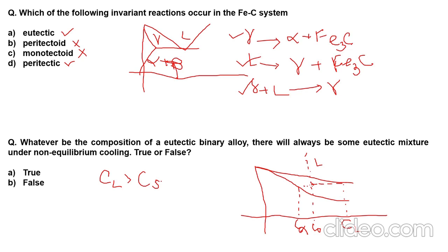So what happens under this condition is that you will always have a tendency for the eutectic mixture to decompose into primary alpha, because we have some liquid that can dissociate into primary alpha during this faster solidification. Once it reaches longer times, or during the final transition, the liquid can dissociate into the eutectic mixture, which is the alpha plus beta.